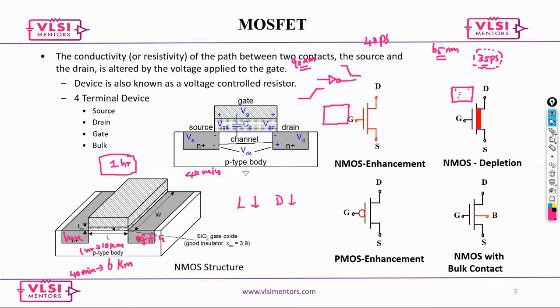Okay. Now, if the length is reduced, then there are chances your delay also gets reduced. Now, let's say your next thing is the transistor width. Remember, any transistor that we draw, we always write it like W by L. For each and every transistor, we will have a W by L ratio.